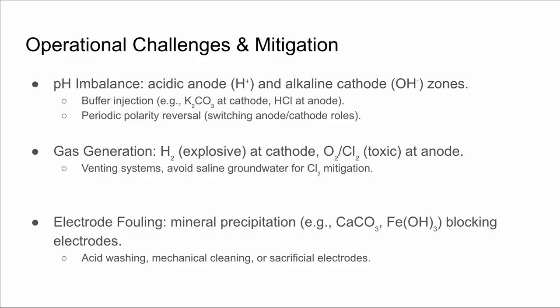We will fix that by injecting buffers at the anode or the cathode to re-establish the pH balance, or we can reverse the polarities.